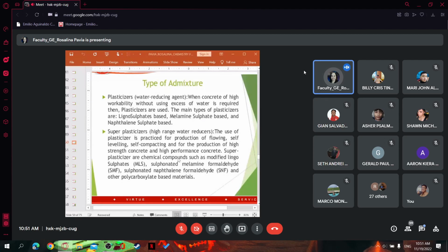Superplasticizers are chemical compounds such as modified lignosulfonates, sulfonated melamine formaldehyde, sulfonated naphthalene formaldehyde, and other polycarboxylate-based materials. Okay, so do you have corresponding types for plasticizers and superplasticizers?